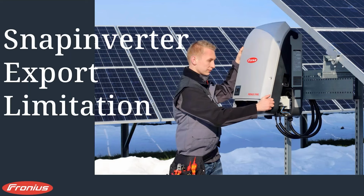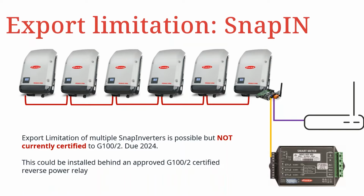Let's have a quick look at the export limitation on the Snap inverters. So even though these inverters are tried and tested, they've been around for 8 or 9 years now, we still have the ability to export limit, and they have actually one real benefit at the moment, which is we can daisy chain these inverters together, and we can export limit multiple devices from one Fronius Data Manager. So the meter connects to the Data Manager, and that is able to control multiple units.